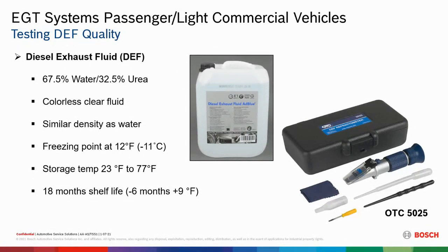But nevertheless, this stuff can't be stored in direct sunlight as well. I know a lot of truck stops put it right in their front window and clear containers like you see here. Sunlight can get in there, and it does affect the quality of the DEF fluid. Don't forget water evaporates. So if it's left open, you got water evaporation, more urea, which isn't good as well. It needs to be pretty much this exact formula that we see here. And it does say 18-month shelf life too, so it doesn't last forever. So don't buy too large quantities where you're not going to use it.